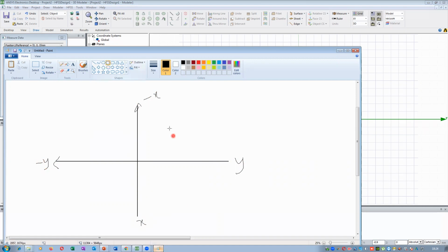Suppose I want to draw a rectangle like this, and the dimensions are this is 5 and this is 3. The units are mm. Now, if you keep it like this, one more piece of information is missing. What is the information? With respect to the origin, what is the location? I can create the rectangle with dimensions 5 and 3 millimeters, but I can't place it exactly where you want. So there is one dimension missing.